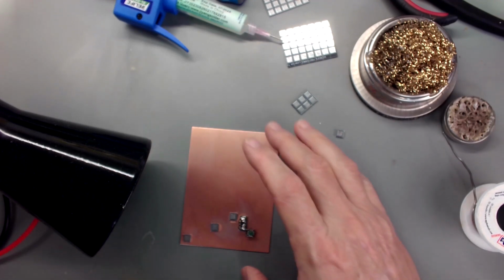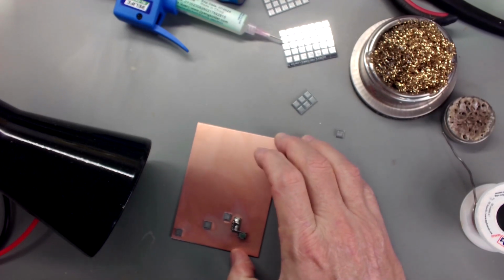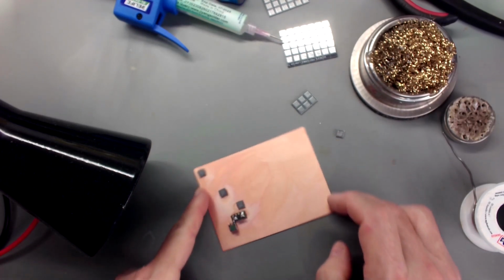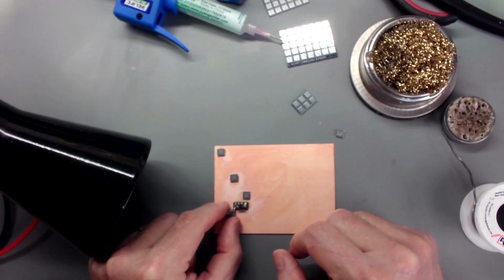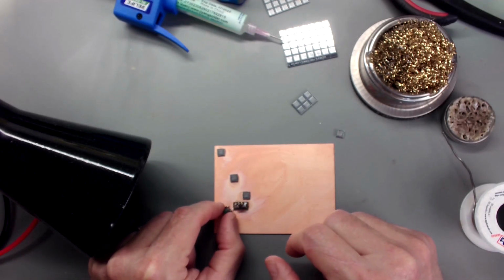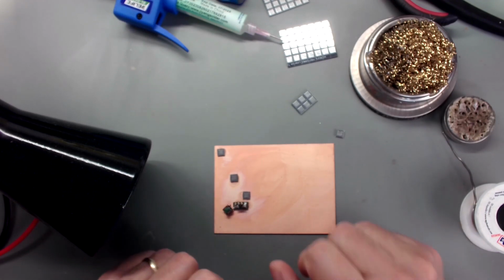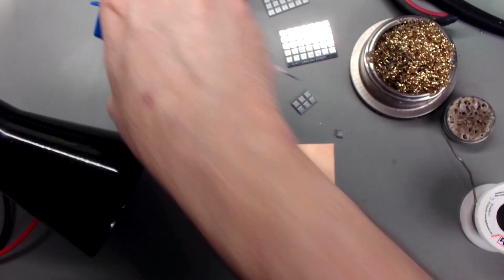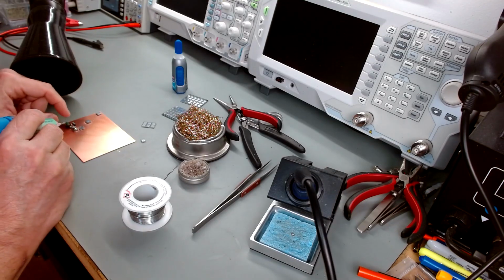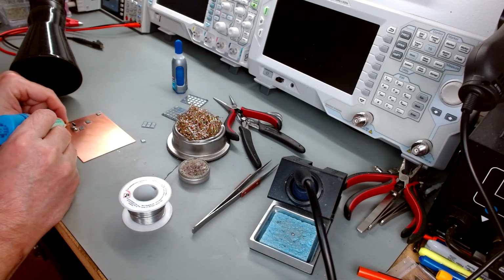And when we're ready, we'll go ahead and put our capacitor there to ground, so I can bypass it with this button. So that's what we're going to do. We're going to put it right over here where it's easy to work with, and we'll go ahead and do that. Let me put just a little flux down there to make sure I get this soldered down well,